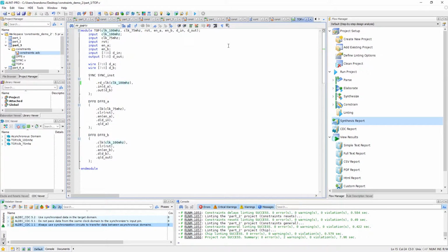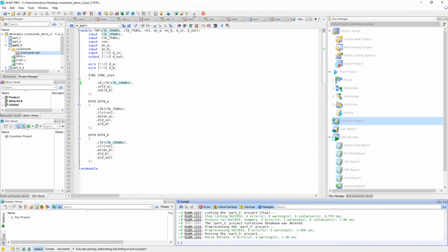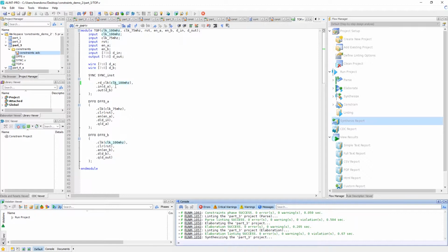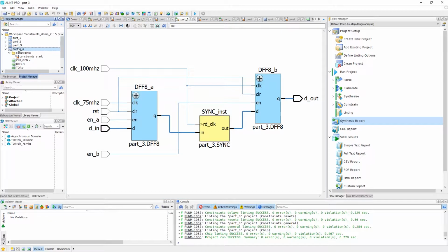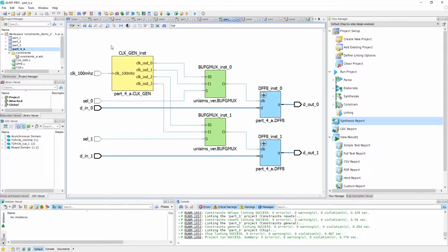By providing the correct clocks to our custom synchronizer, that is the clock of the destination domain, we can now see that our design is compliant with those previously violated rules. And with that, that'll mark the end of our library function examples. Of course, more library functions do exist to cover other types of modules, which can all be found within the command reference guide. But I'd like to now go over one more example to wrap up some more on block level constraints.